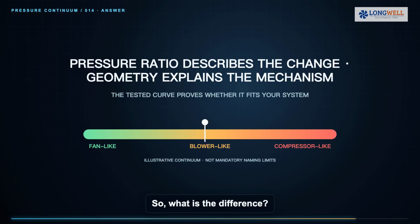So, what is the difference? Fan, blower, and compressor are useful families, but their boundaries overlap. Pressure ratio describes how much the gas state changes. Geometry explains how the machine creates that rise. The tested curve proves whether it can serve your system. Select from the duty point outward, never from the label inward.